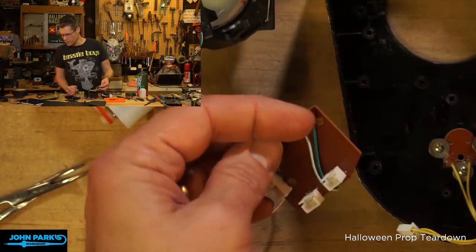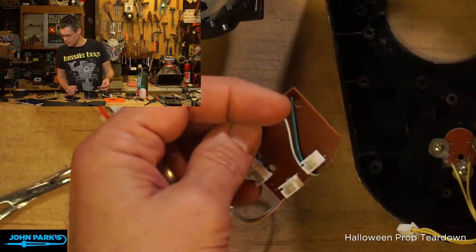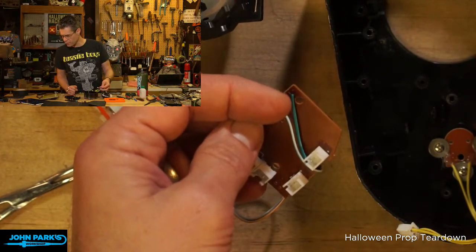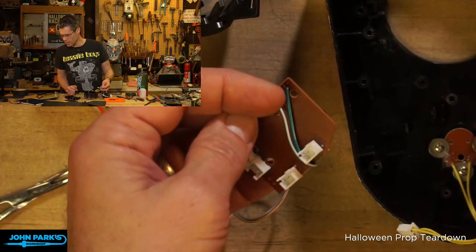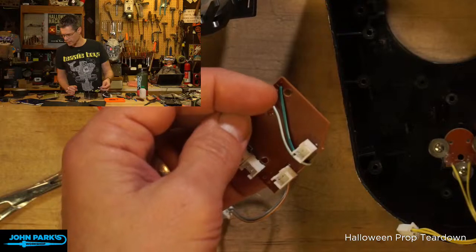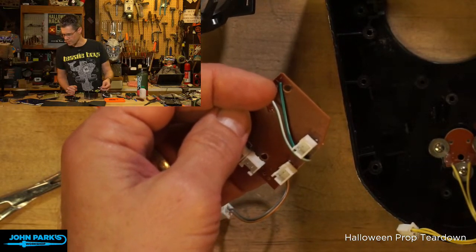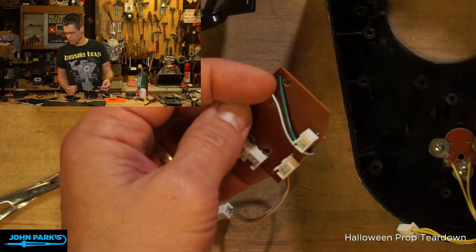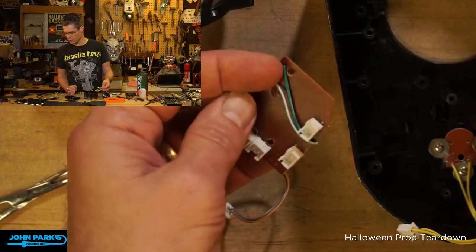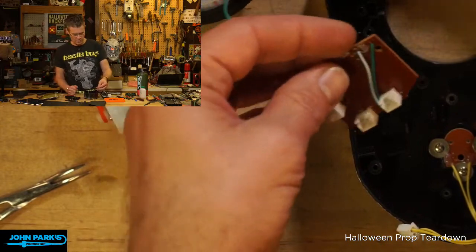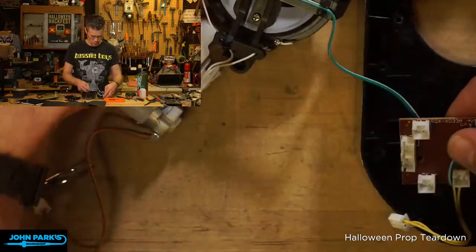Hamslab says, right now I'm working on using EL wire to make a lightning effect. If you pair white and blue or white and purple and flash them really fast, white 20 milliseconds, the other one 20 milliseconds, it looks really like lightning. Oh, that's cool. SparkFun has a shield to control 8 EL wires, and I got a Metro ESP32S2 from Adafruit and EL wires where I could find them. I'm putting it together after this. Oh, that's very cool. We'd love to see that. Please show those off in the show and tell.